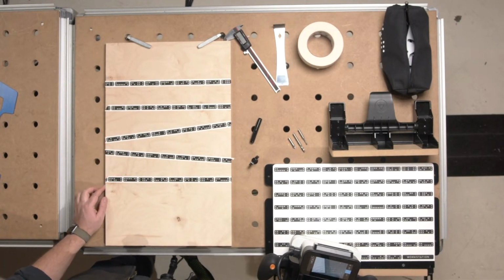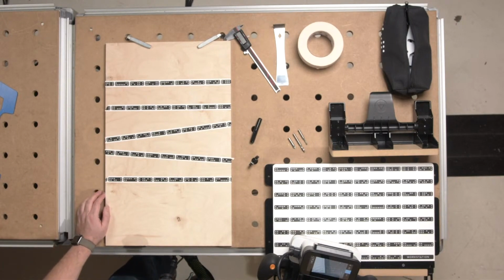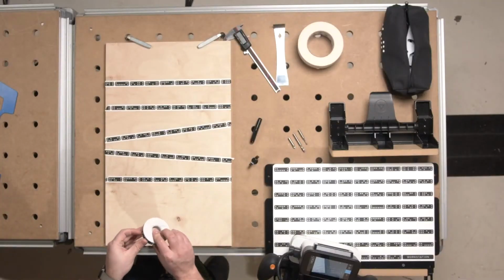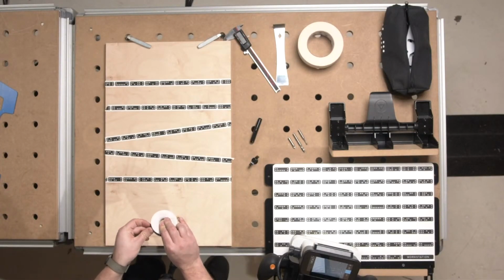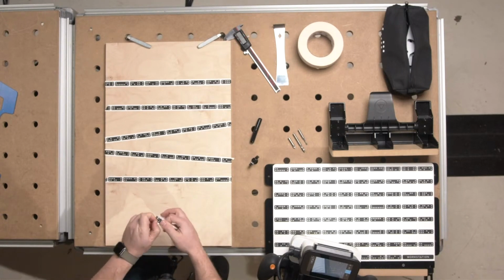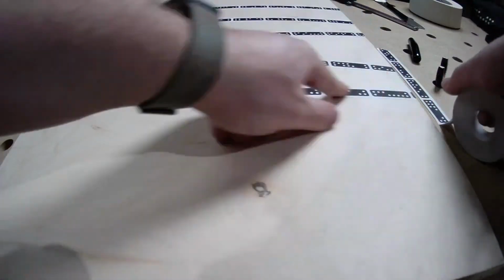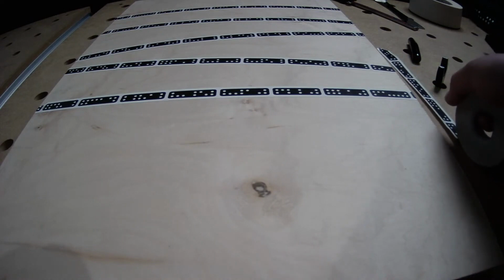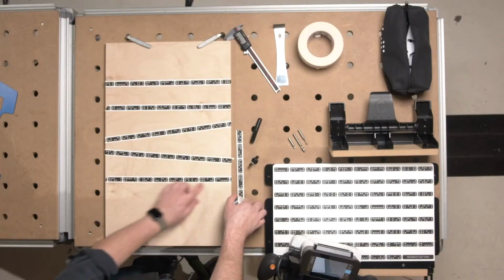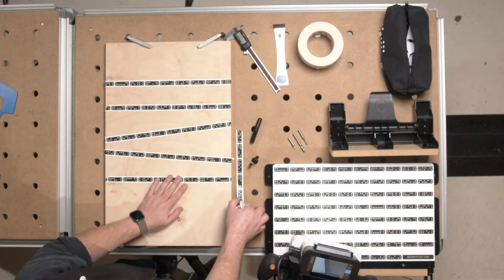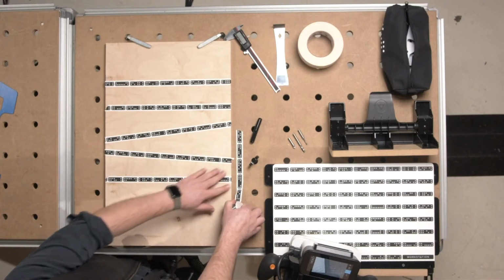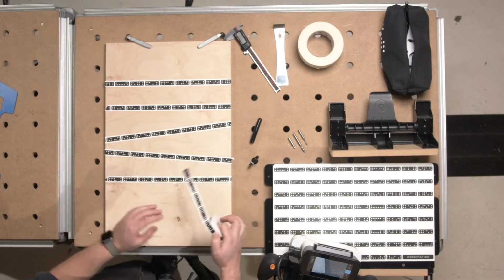I was going to say, maybe for the new users, one of the really important parts about tape is it being very flat. So you don't want to put it on cut boards, and you don't want it on different levels, because that will confuse Origin. True. Tape on multiple levels is a no-no. If I were to put tape down here, half an inch above this plywood, onto my table, that really wouldn't work very well, because the tape would be on multiple planes, and Origin is just going to refuse the tape that it sees on a different plane. It's not going to be useful to you.